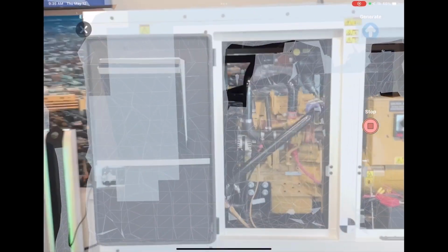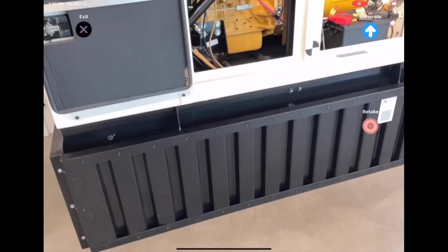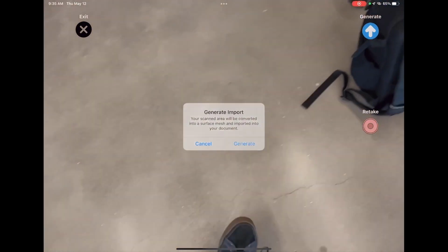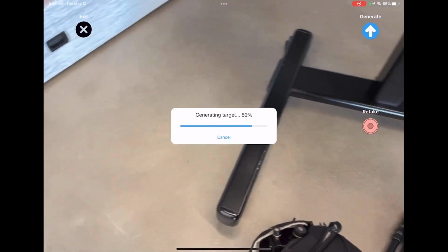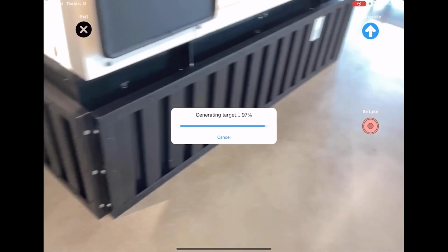Now, natively inside of an Onshape document, you can initiate the 3D scan. Pick up your device, tell it to scan an object, walk around the target, and notice that you will see the scan layered over the physical object in augmented reality in real time.